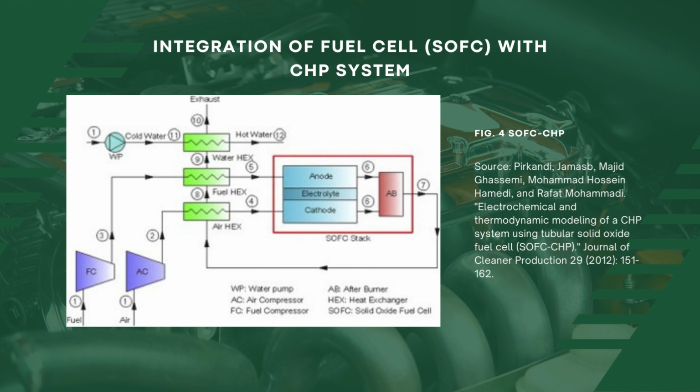These recuperators are basically heat exchangers. The energy used in a building includes heating, cooling and electrical load, and the proposed SOFC CHP system should be able to provide them. The heat obtained from the third recuperator, that is the heat exchanger, can be supplied for the heating load and sanitary warm water for the building in winter time.